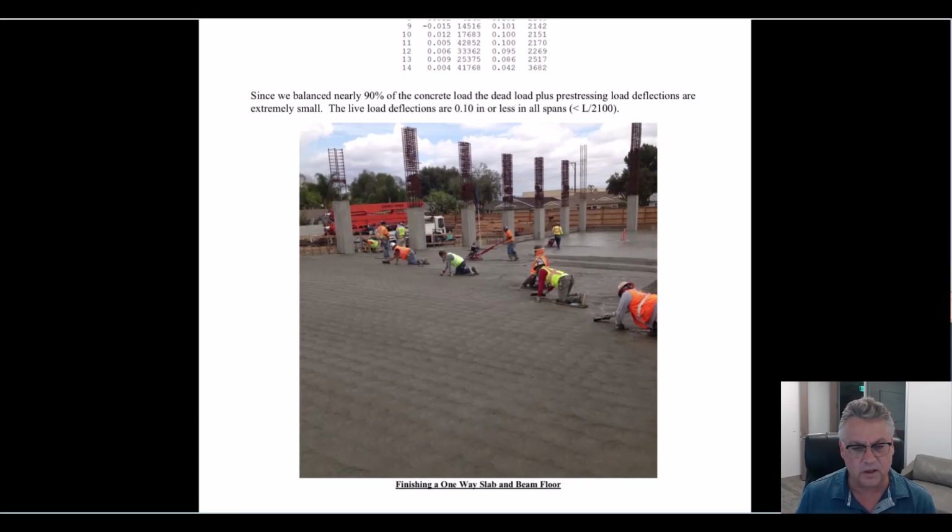You don't want a smooth concrete surface as you're driving around. You don't want wet wheels to spin. So these people are putting in a swirl, which not only looks good, but actually has a function to it. It helps the tires grip, and when you're walking, helps your shoe grip to the concrete.